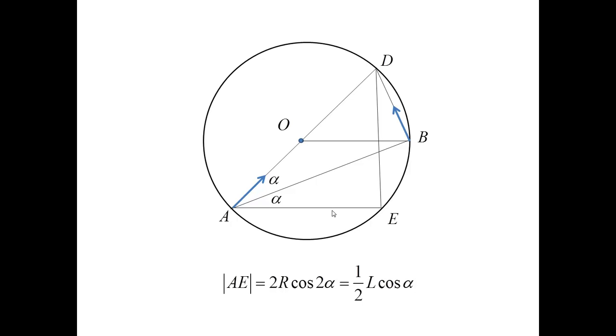Next, I would like to use the point D as the reference point for the moment equation. The forces NA and NB intersect the point D. Therefore, their moments about D are equal to 0. It means that the moment of the weight with respect to D has to be also equal to 0. It means that the arm of the weight must be equal to 0.